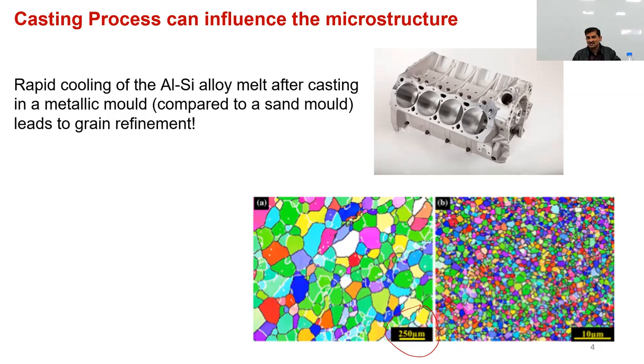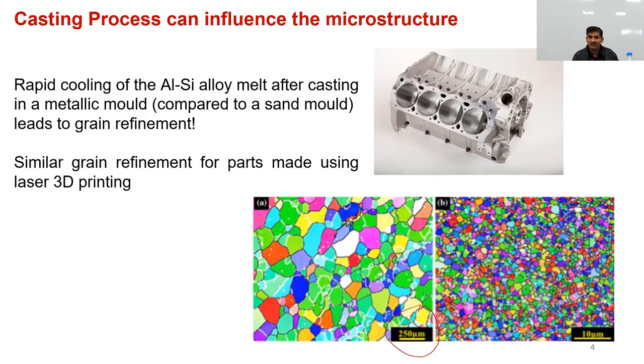Normally, these two properties don't go hand in hand. If you increase strength, typically it comes at a trade-off, and that trade-off is lower ductility. So that's why grain refinement is an interesting mechanism whereby we can actually get the best of both worlds. That's why there's a lot of interest in refining grain size by various technologies. And solidification happens to be one of those technologies where we can actually play around with the kind of grain size that we get in the material.